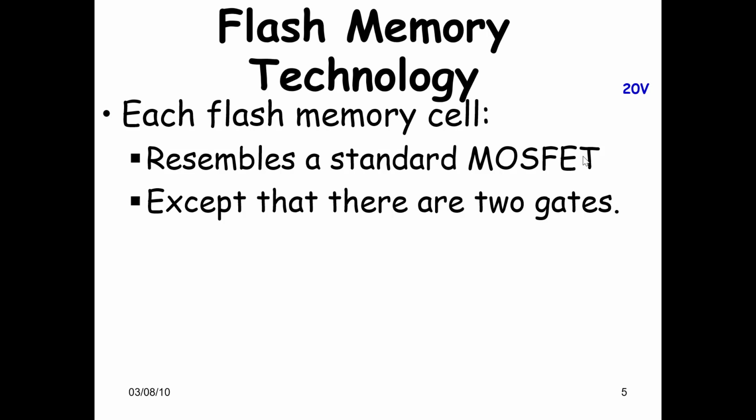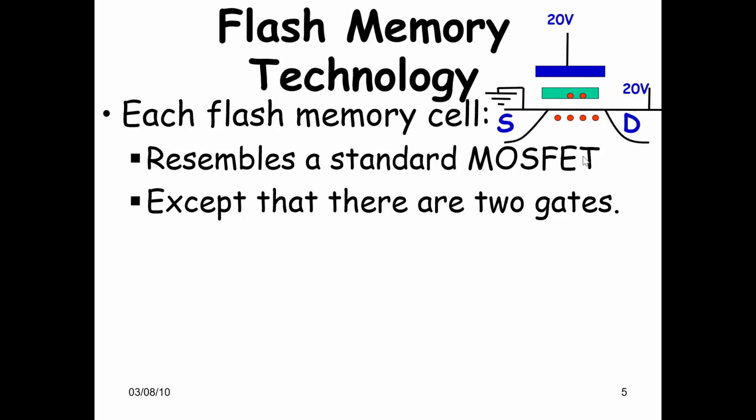So of course the idea is that we have the notion of this floating gate transistor where large voltages are applied to either suck up electrons towards the gate and trap them over here in the middle, or you can apply a negative voltage to push them back into the channel region, right? So this is a typical NMOS MOSFET with the source and the drain, and you can see the channel region over here.